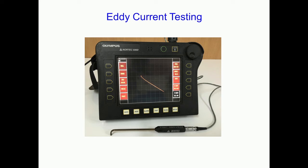So, this box has the necessary electronics, the connectors, the battery for powering it, everything inside this box, and then through the connectors that you have, you can connect a probe. You can see a probe over there lying in front of the system, in front of that box. So, you take this probe and then you have to bring it near to the sample surface. You can touch it on the sample surface and then you could see the eddy current signal coming out.